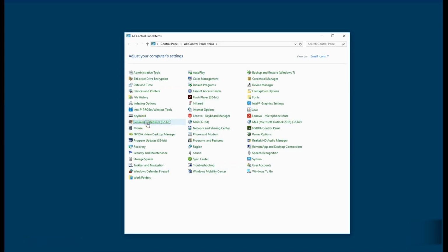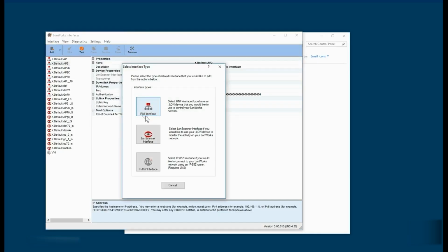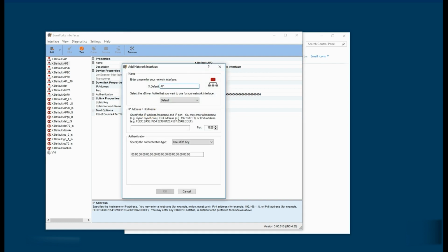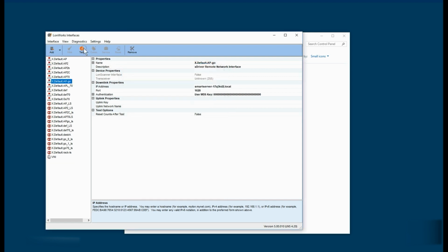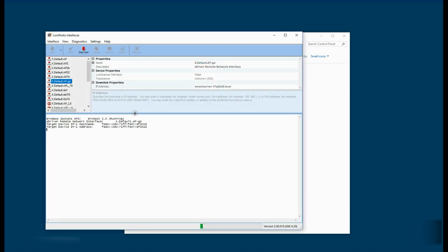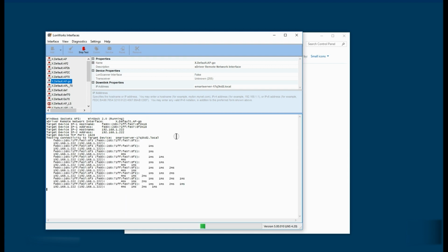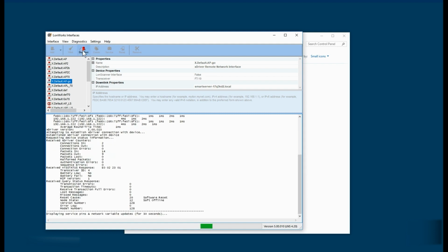With the RNI resources enabled on the SmartServer, we can go ahead to the LANWorks interfaces applet and add the interface to access with OpenLDV and the IzoT CT stack. I'm using the hostname.local to address this device, knowing that even if the network conditions change, as long as my PC and the SmartServer are on the same subnet, hostname.local should resolve with MDNS.